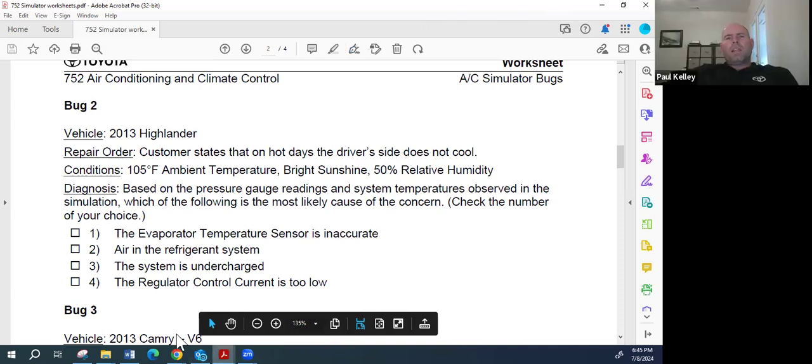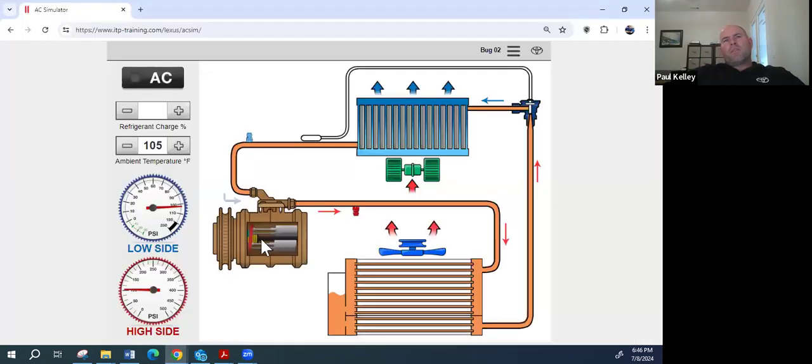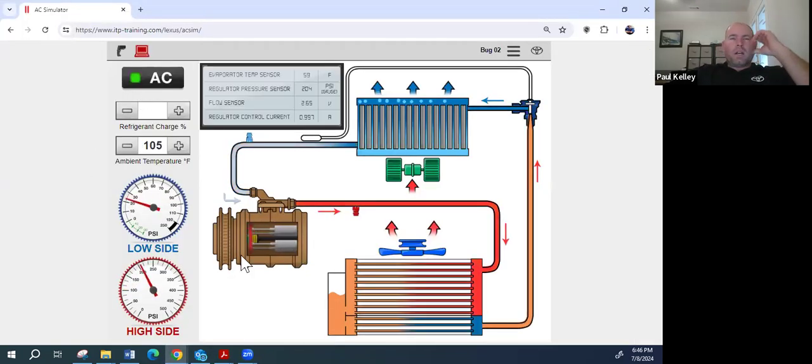Sometime I'd like to jump a little bit further on that because I've seen that firsthand. If you were to kick the AC on and there were moisture in the system, a lot of times what you'd see is, picture a little blob of water. On the low side, if the water's here, it's kind of going through.